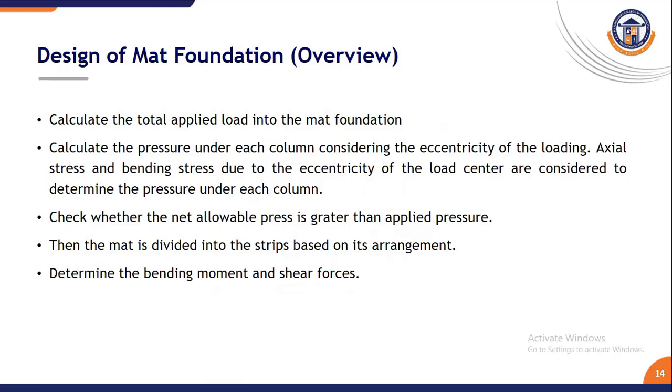Okay, here the conclusion from the design of mat foundation: we need to calculate the total load from the structure, after that soil pressure, and then safe bearing capacity, and then bending moment and shear force. All the details we need to have ready before designing of mat foundation.